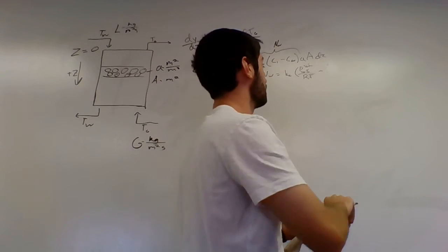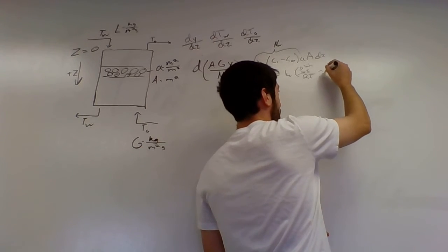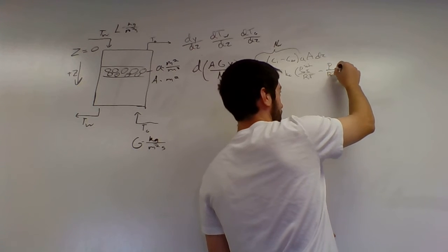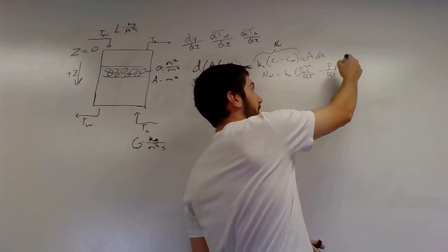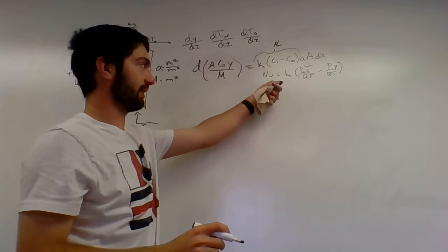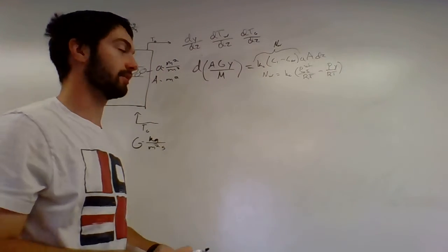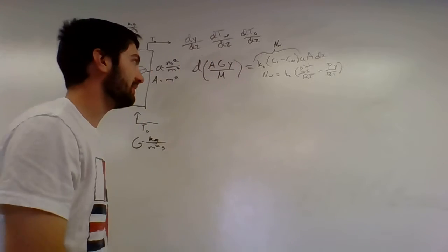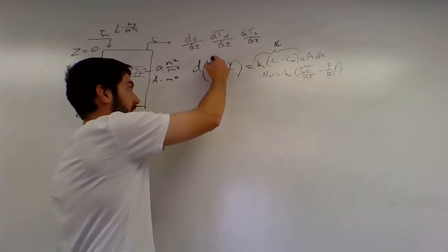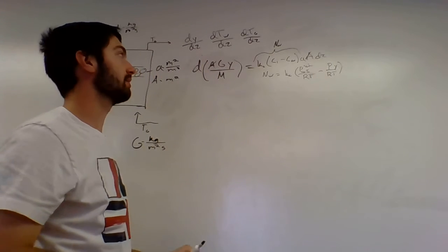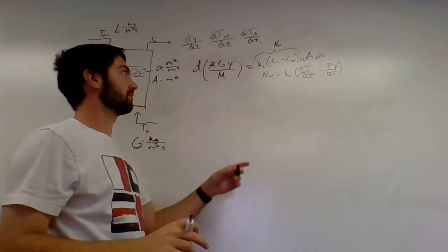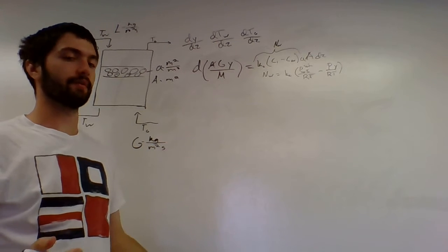The total pressure over RT, and since we want the concentration of water, we want to multiply by the mole fraction of water in the air. So we can think of that term as just the molar flux of water. So now we have this cross-sectional area term on both sides that we can cancel out. And then we can draw the constants out of the differential.